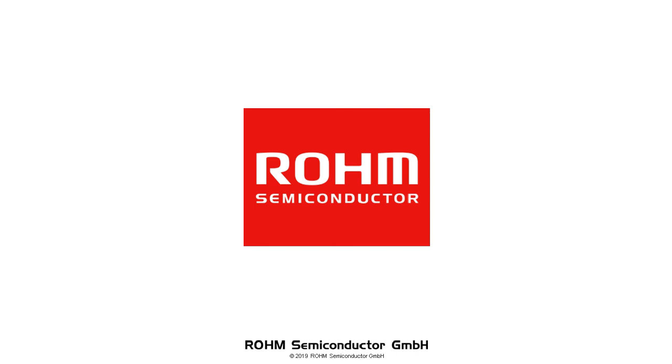The next question we had is, what is the difference between the BD71847 and the BD71847A? Okay, so the total description why we had to go to the 71847A can be found on our website in the errata for short notice. There was a minor bug found in the chip in some very seldom circumstances when the input voltage is very, very low. During the OTP readout, there was a problem, as said, and this was corrected. Means at the end of the day, there was a metal mask update, which was necessary to fix this issue. So we are just supporting and supplying the 71847A. The version with no A won't be supplied to the customers anymore.